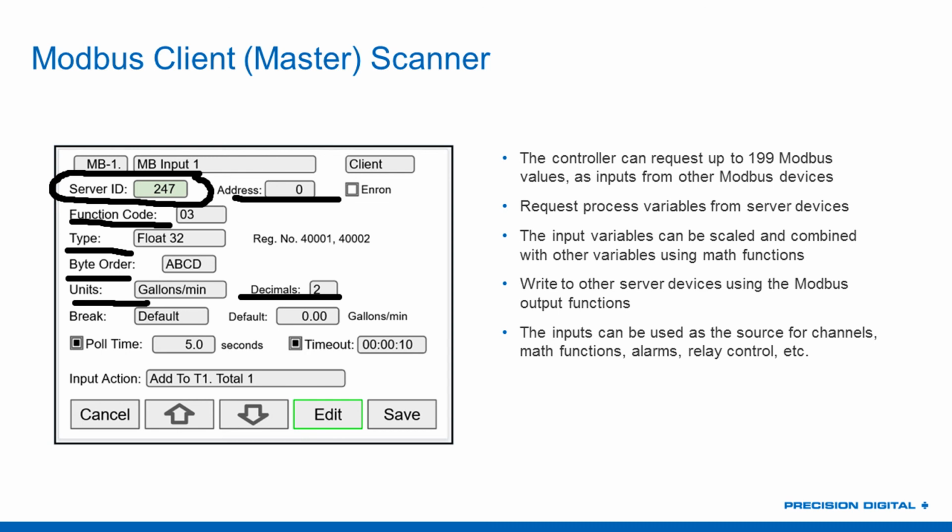Those can be programmed. Everything on the bus has to have a unique address or a unique server ID. And so that will vary application to application, transmitter to transmitter. But it's something that you just program in there, and so you just want to make sure you check that one. And that's something you can look up, but you've got to look it up in the programming of the transmitter. It's not going to be just spelled out for you in the manual, like, hey, this is ID 1, because you could have 10 of these on your Modbus RS-485 line, and every one of those has to have something unique. So that's not a manual lookup, which I think you seem to get. I'm just stating that is something you'll have to check on your transmitter.